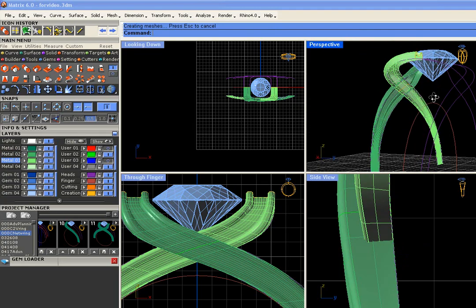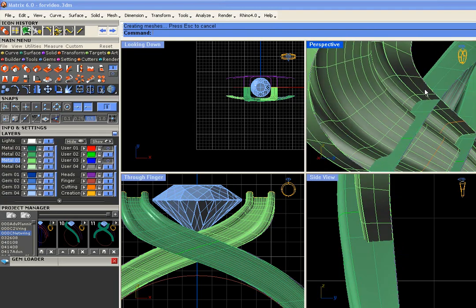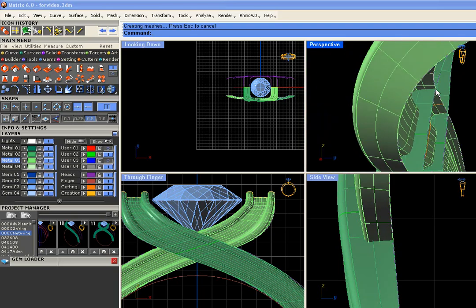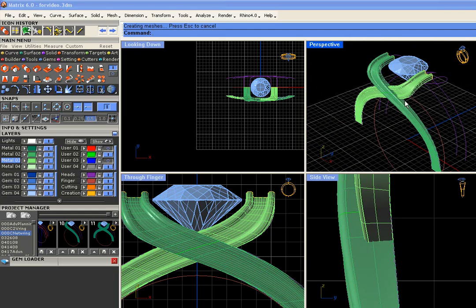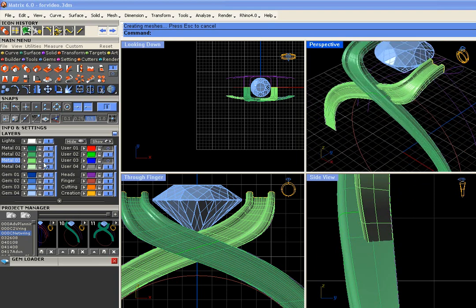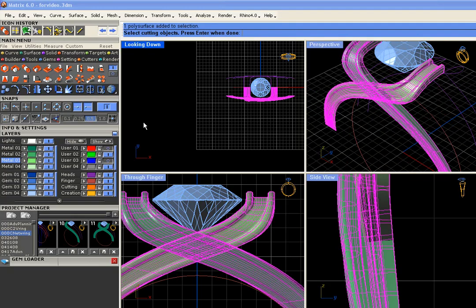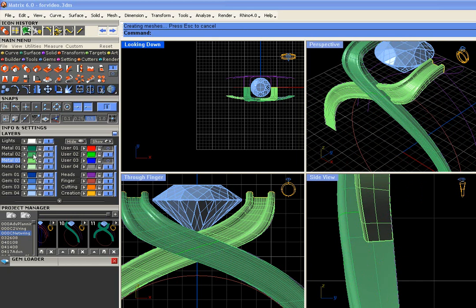Great. The thing that we didn't change was the fact that these 2 profiles lay both of them on the rails, so we should be able to split one with the other. Famous last words. To do so, right-click on the layer color and run the split command and split it with the other layer color. Enter. One surface split into 3 pieces.